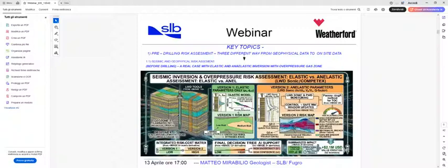So the second model is using the inversion with inelastic parameters. We can apply different filters and different types of inversion to seismic data, and substantially we consider that in XYZ we have different compression, so we can consider the subsoil not totally elastic.